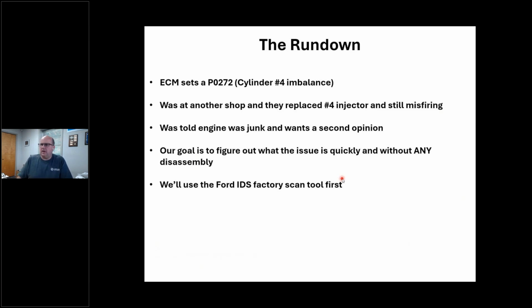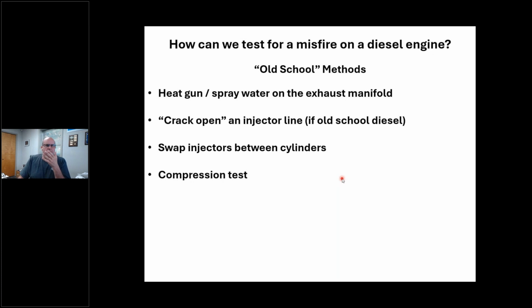Now we're going to use the IDS. We can do a couple things here. And for you old school diesel mechanics out here, on a misfire engine, we've got a heat gun. You could stick a heat gun at the manifold. We could use water, a spray bottle. I could crack open an injector line on an old school diesel.